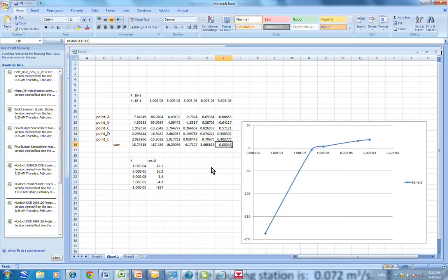I don't want to go through it here because it's pretty much the same operations that we've just done, but you're adjusting recharge instead. What this does is it shows that you can calibrate a model using the hydraulic heads by either adjusting the conductivity or adjusting the recharge. And if you fix one and adjust the other one, you can match the heads equally well. So this is a problem because it means that there's no unique calibration for your model if you just have hydraulic heads.